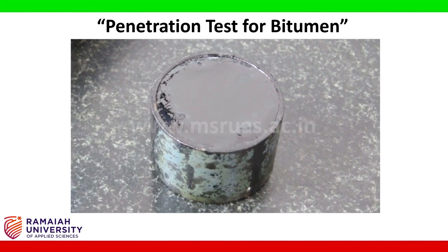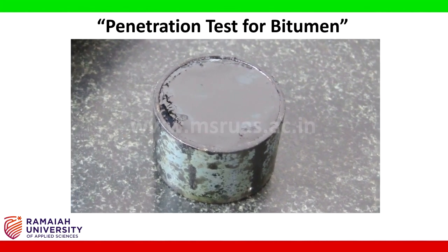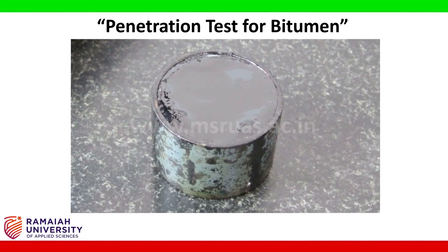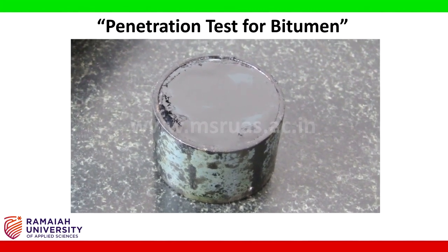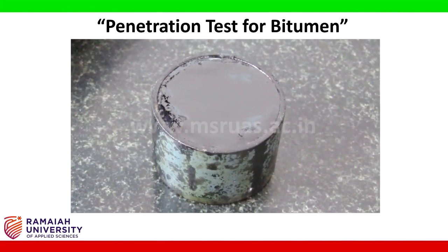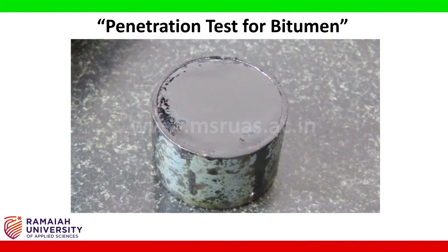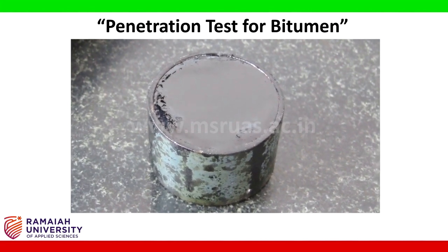Once this is done, we are supposed to cool this sample in air for 1 hour, and after air cooling, 1 more hour in water before testing.